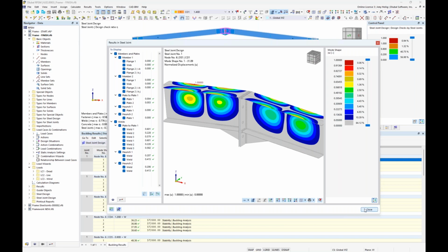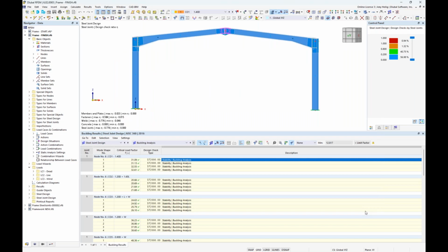So buckling is certainly something that is not easily accounted for with hand calculations, or analytical calculations for connections. So we have the ability here to carry out this additional analysis and determine that if buckling is a concern, do we need to increase the thickness of these surfaces, such as the web members or flanges, or maybe we need to add additional stiffeners with those component input options.